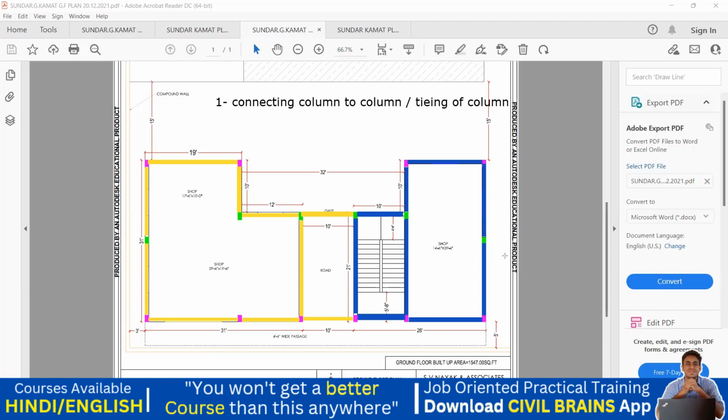So this is the basic understanding of what I have done, and for the same drawing, we'll see how the structural engineer has done it. Now you can give naming to this. Naming can be anything, but the usual practice we follow is that we start from left to right, and then from bottom to top. This is a typical pattern we follow when we write the names for the beams. Again, it all depends. You can even follow right to left, or top to bottom, but most engineers prefer left to right and bottom to top.